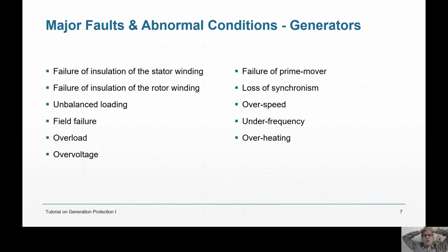It's always 49.97, 49.98 at the most, low by 0.02. High, 50.01, 50.02. It will never be 50 or 50.5. You see, that is very important. To maintain the frequency is very important. Otherwise, the generator will be damaged. The system will be under problem, that is another thing.